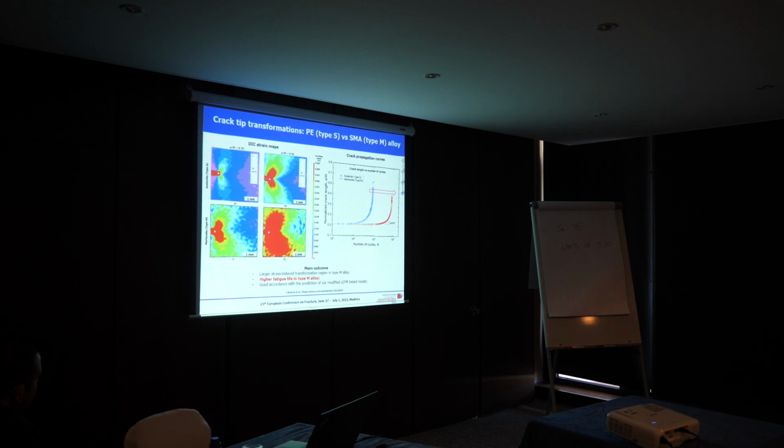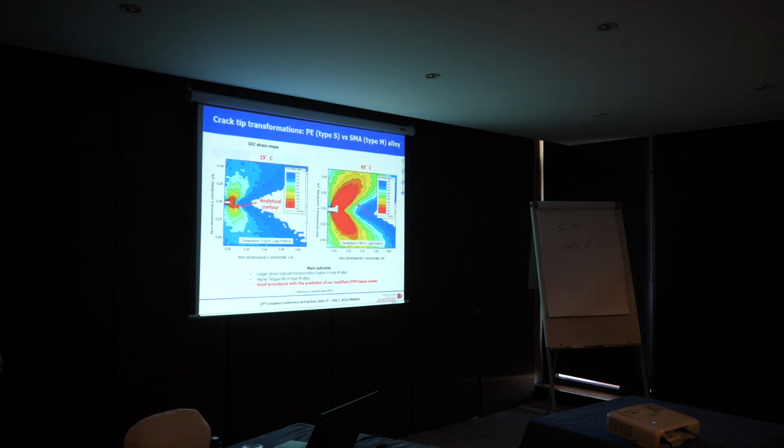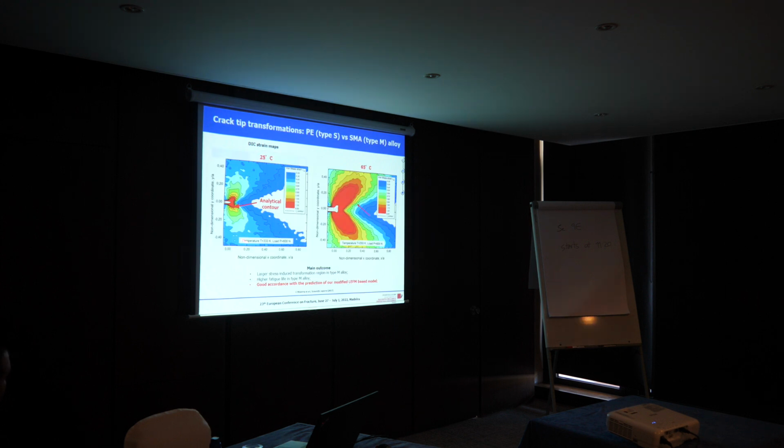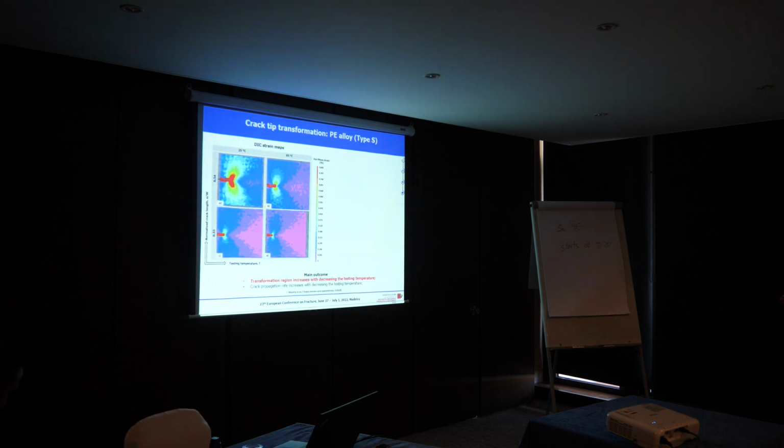We have also observed a large difference in the fatigue properties, I mean, much higher fatigue life in type M alloy compared with type S. We also compared DIC and our analytical model in terms of transformation contours, and we obtained very good agreement.